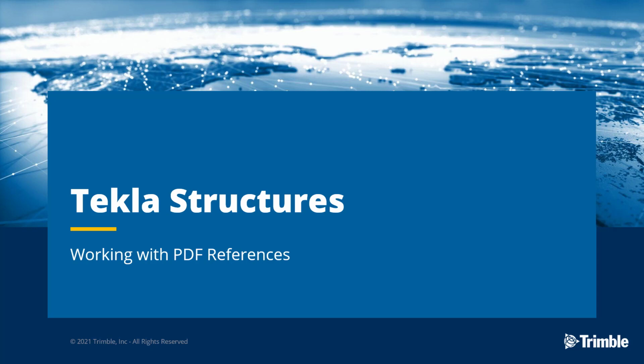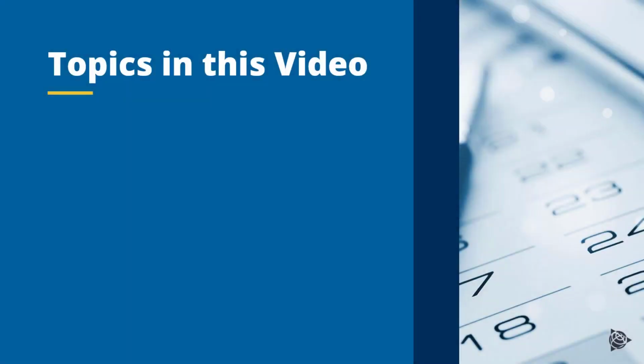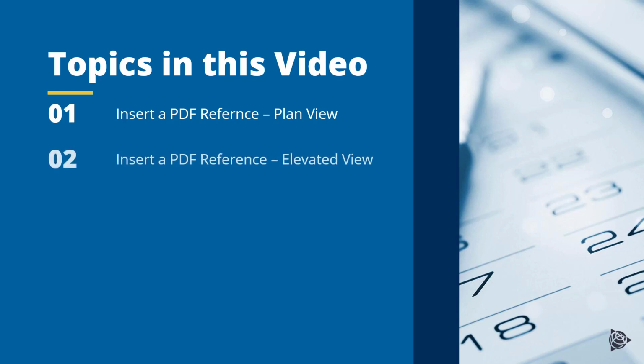Today in this video, we're going to be discussing working with PDF references. For this video specifically, we will be covering the following key points. How to insert a PDF reference that contains a plan view, so that it is orientated horizontally in our model. Also, we'll cover how to insert a PDF reference that has an elevation view, so that it is orientated vertically in our model. And lastly, we'll cover a couple of tips and tricks for working with PDF references. So with that, let's begin.